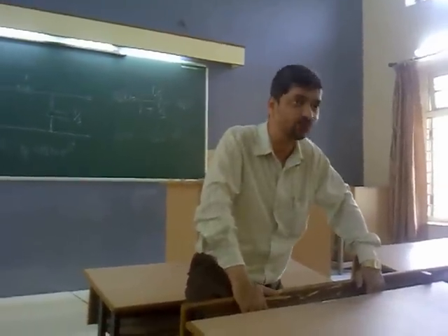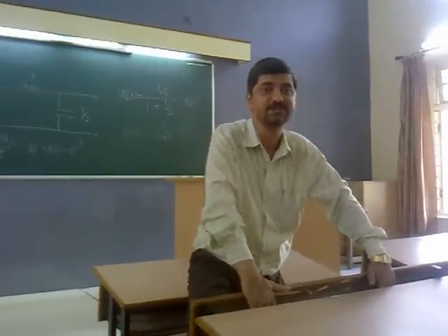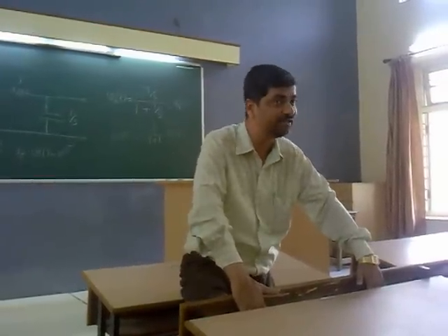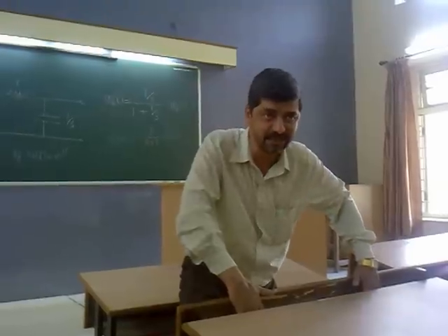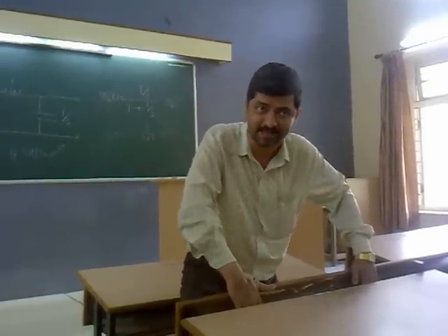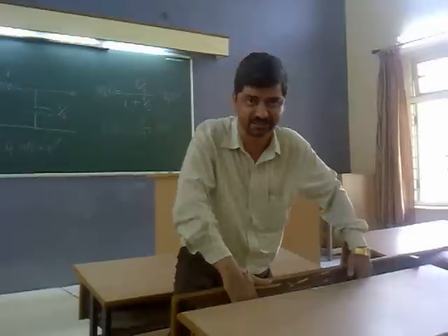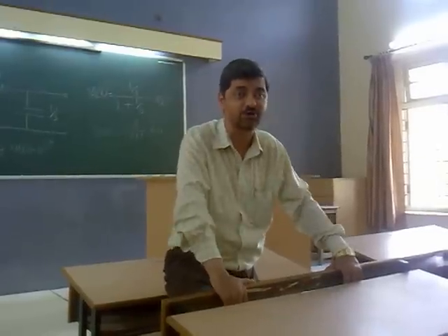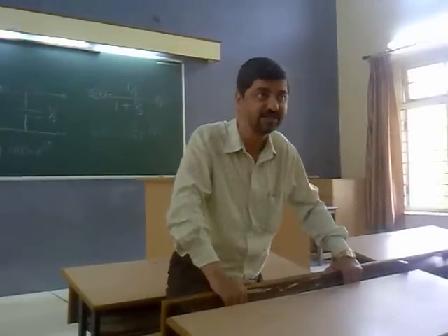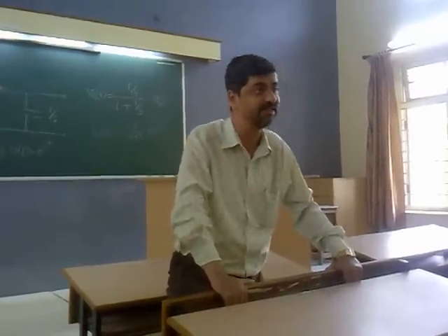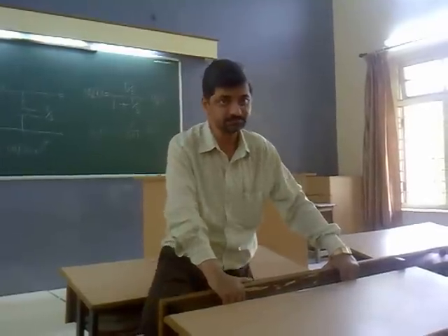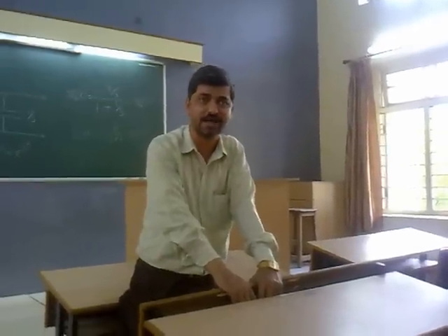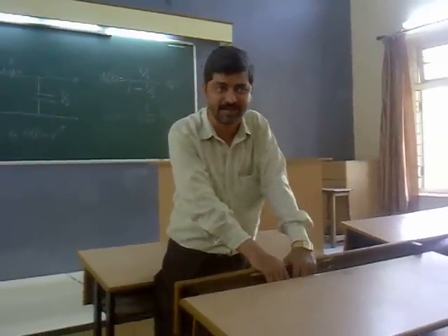And I can say that V in t is equal to the summation of V1t plus V2t, with both V1t and V2t may be non-realizable, but Vt may be realizable if it works out to be one dimensional. And it really happens so if S1 and S2 are complex conjugates of each other. In that case, their summation is one dimensional. For further simplicity, we can take sigma to be 0 and only concentrate on e raised to j omega t.